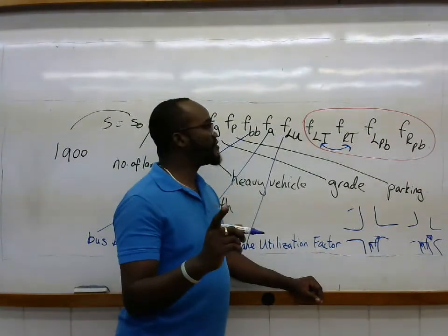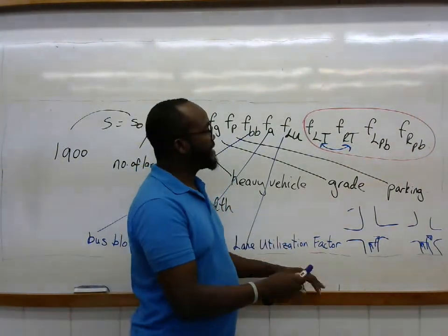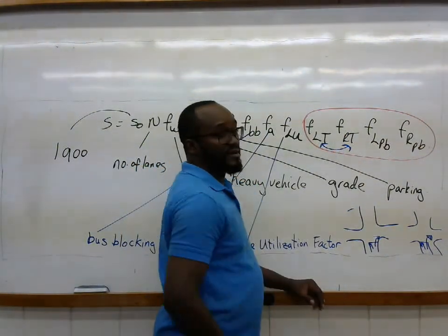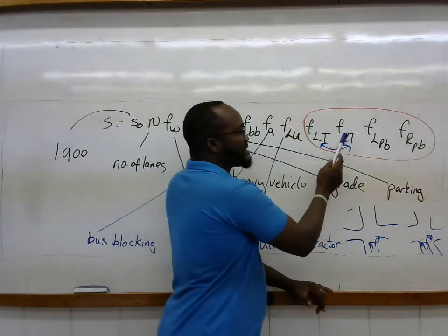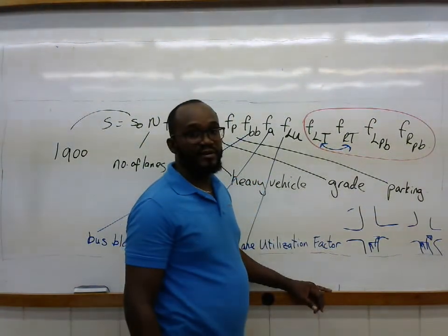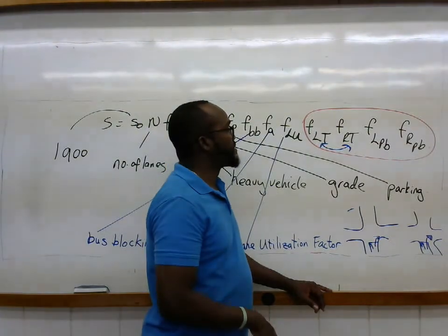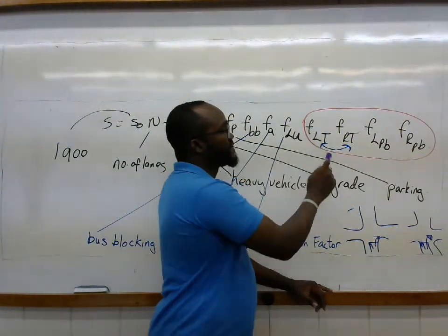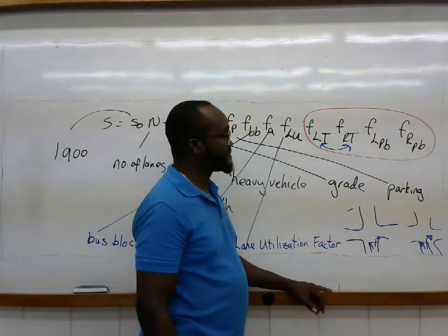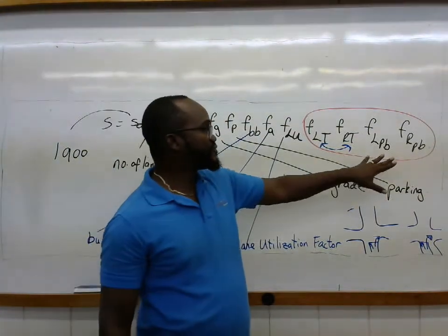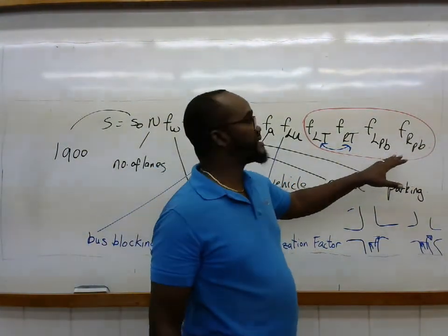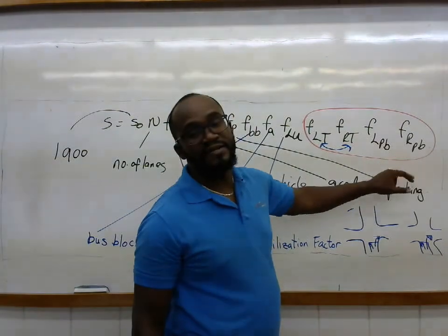So remember the turning movement counts that we had. When you apply the formula, ensure that the right turns that you actually recorded are switched for the left turn value and vice versa. Same thing applies for the last two terms. These last two terms represent the pedestrians and the bicycles.